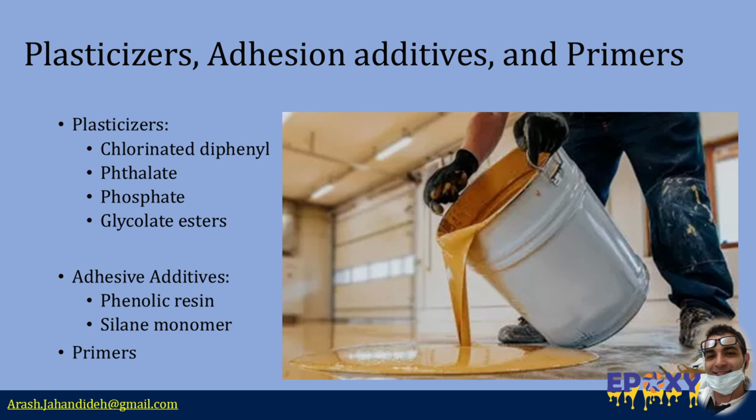For unusual or difficult building surfaces, manufacturers often offer specialized primers tailored to the specific sealant systems. Masonry primers, for instance, may contain chlorinated rubber, modified phenolic resins, and plasticizers.